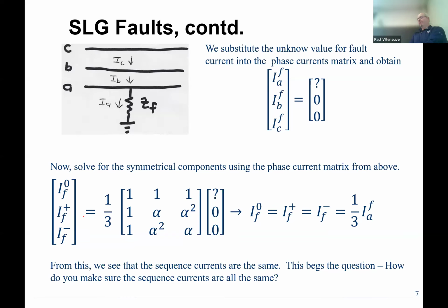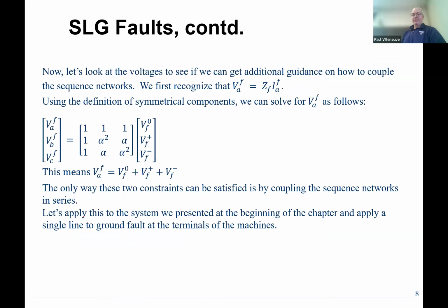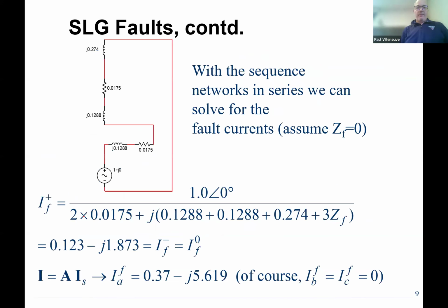Put them in series. So I'm going to put them in series, but I want to make sure that my phase A fault voltage is going to match the three added together. So if I plug in the value over here, you'll see that I got VA. This is just the definition of symmetrical components. So you're just going to add up all three.